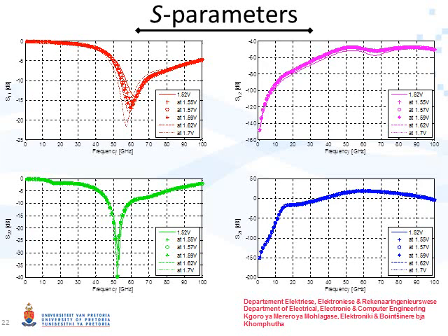However, the input and output ports of the power amplifier still remain well isolated. The S22 achieves a minimum of -39.71 dB at 52 GHz. This is because of the load-pull matching technique being used at the output stage of the power amplifier. The small signal gain S21 increases from 16.56 dB to 20.66 dB because of the bias voltage increase from 1.52 volts to 1.7 volts.